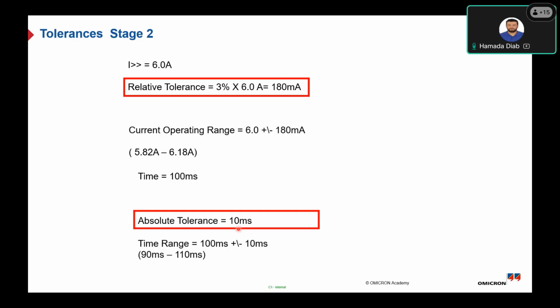But here is a different and most important feature to take into consideration, which is the relay operating time. Normally, to take the feedback from the relay binary output to the CMC binary input, it can take internal processing time inside the protection relay, which can range between 20 to 30 milliseconds. So we have to take into consideration also the internal processing time of the protection relay.